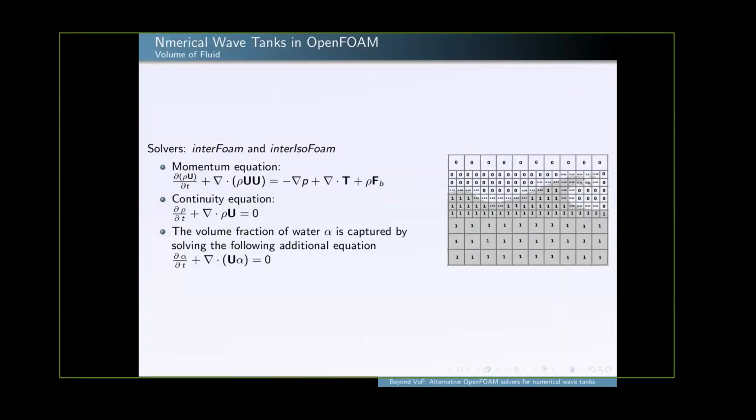So looking at the solvers, the most popular method is the volume of fluid method. And you can find those in the solvers interFoam and interIsoFoam. It has the iso vector. So when you're trying to develop a numerical wave tank, there are the equations that they solve. I don't need to go into detail for those, but I just put them up because I'll show them later when I'm talking about the wave makers.